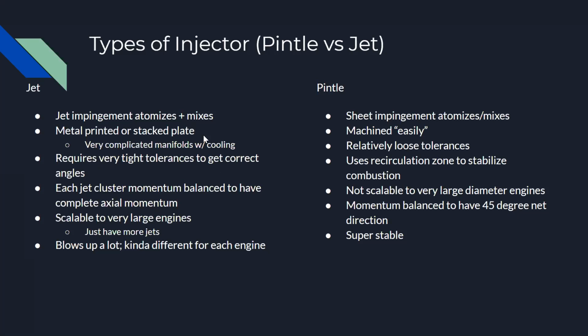Oh yeah, the other thing is we did deal with it on the Methalox engine, when we had to get a replacement printed. I think I mentioned that it was metal 3D printed, but when we got it printed, a lot of the jets were clogged because the printer's tolerances weren't high enough. So that was a pain to deal with. But anyway, on to some more about pintles, my personal favorite.